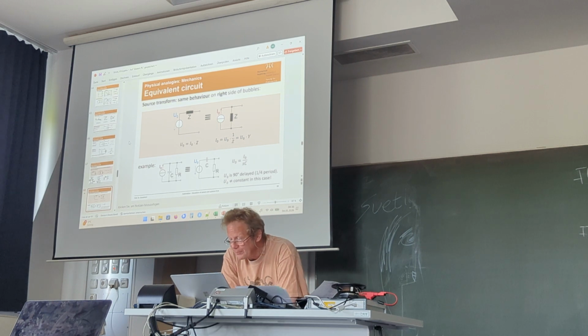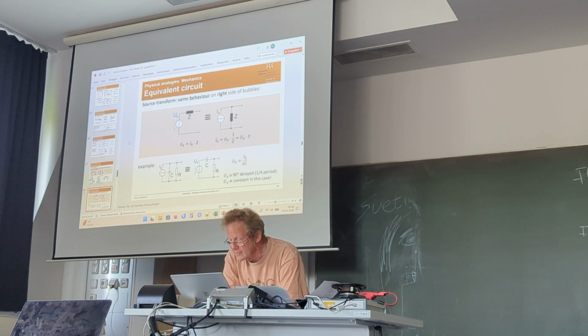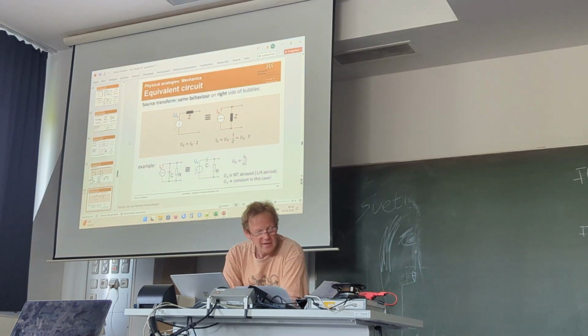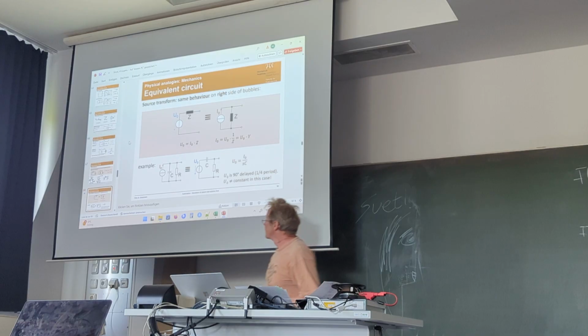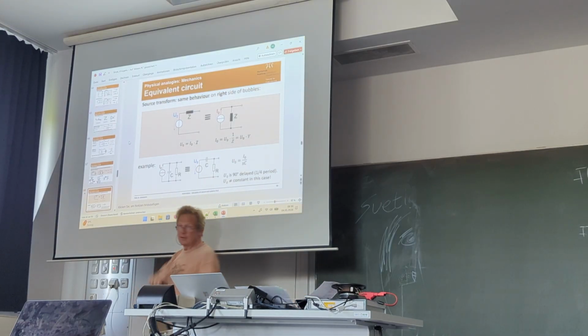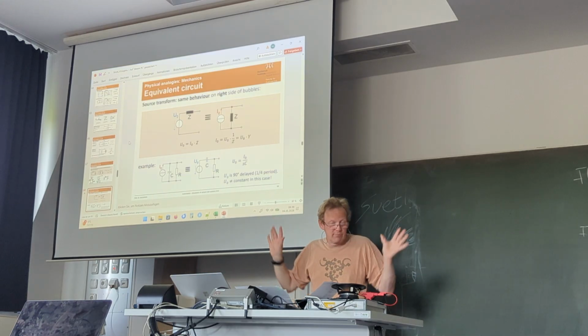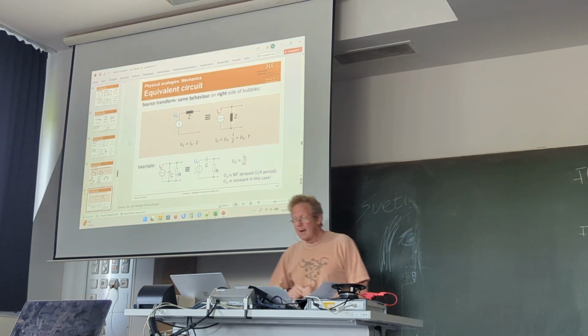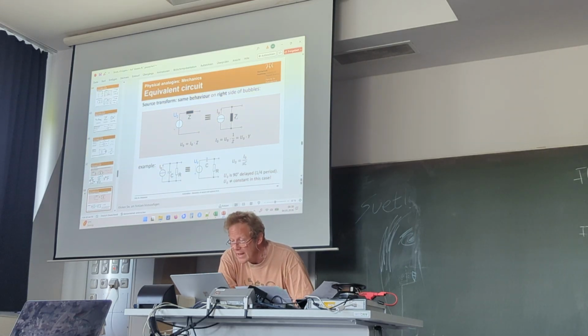Then something else, for the electric world where I never really felt a useful application, but in the mechanical world it can be used for something. It's called the source transform, and it says when you have a voltage source with a serial internal resistance, or just any serial resistance, you can transform it into a current source with the same but parallel resistance.